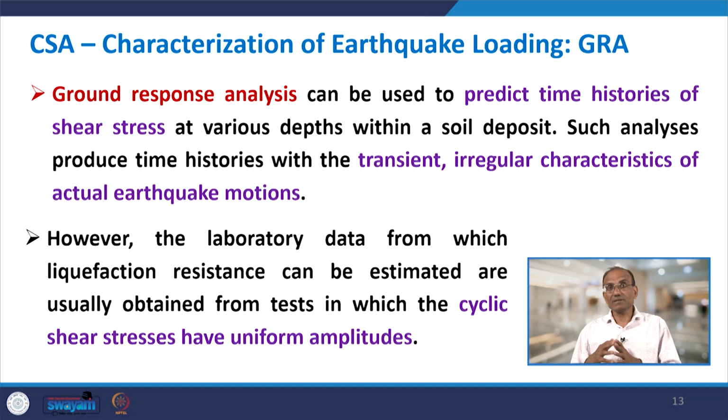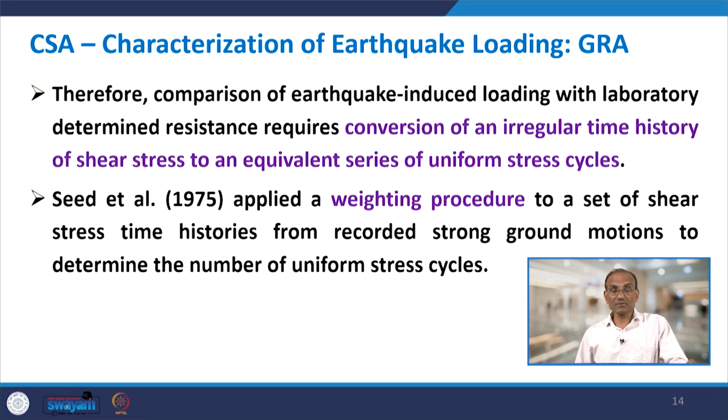So, if you want to compare liquefaction resistance, particularly when you find the liquefaction resistance using the laboratory data, then you need to have a uniform time history. That means the peak values are equal, and here the peaks are not equal. Therefore, comparison of earthquake induced loading with laboratory determined resistance requires conversion of an irregular time history, which has been obtained using GRA, to an equivalent of uniform stress cycles. Some peaks are high, some peaks are low, but we require a uniform shear